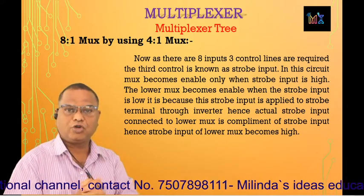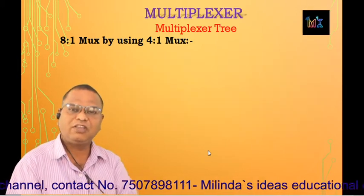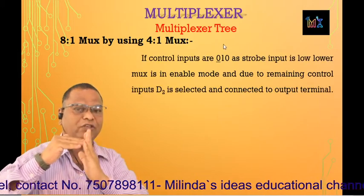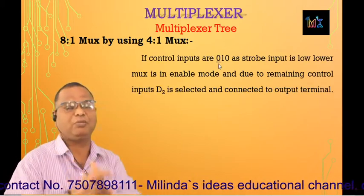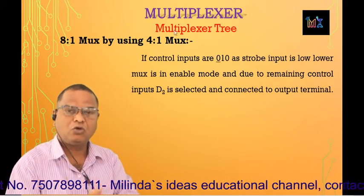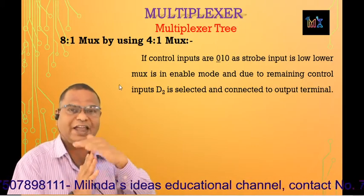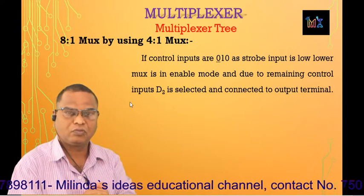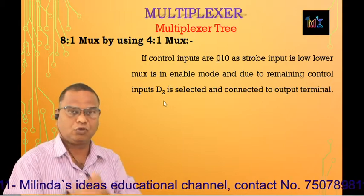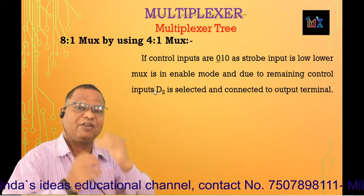Now let us go through an example. For example, if the control inputs are 0 1 0, as S2 is 0, the lower mux, that is M1, is in enable mode. And as per the remaining control inputs, that is 1 0, the data connected to I2 is selected and fed to the output terminal of the mux. The data connected to I2 of the lower mux is D2. So in this case, from D0 to D7, the data D2 is selected and fed to the output terminal.